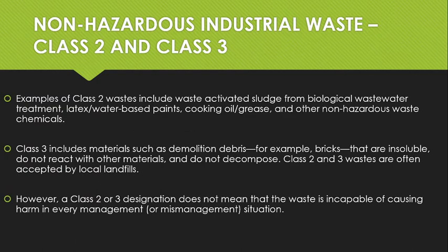Class 2 and class 3, these are the most non-hazardous. These are the pretty benign stuff. So we're looking at latex and water-based paints, cooking oils, and food grease. Those are the biggest or most common examples of class 2 waste. Which, also for another example, I guess, would be the sewage and the rinse water that we tested earlier for the metals. Well, that came back all non-haz. There was nothing hazardous there. It doesn't have high hydrocarbons, over that 1,500 parts per million. So it'll be class 2.